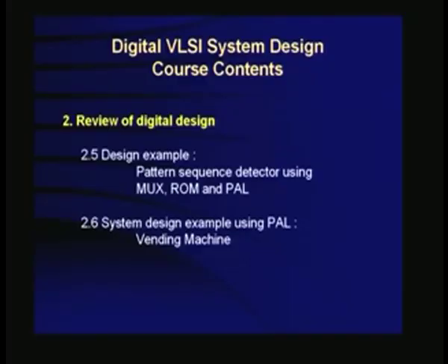This will depend on the system. The system will give the status information back. How do you do that? And then from that you draw the ASM chart. From there you do the individual design of the controller and implement it using a ROM and a multiplexer or a PAL. All that will be done in this course.